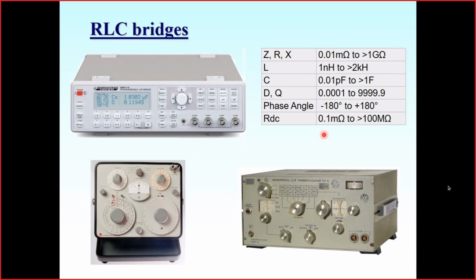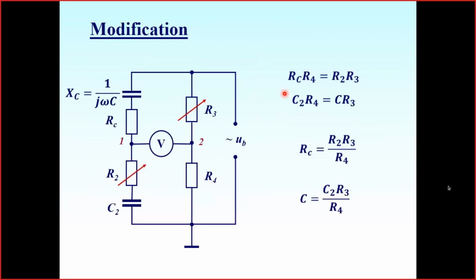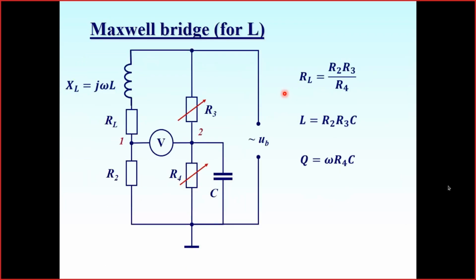We use bridges that measure any parameter we wish, for the estimation of single electronic circuit elements like capacitors, resistance, inductivity. Other parameters may be measured too. For inductivities, it measures not just the inductivity, but also the quality factor. It measures phase angles, and so on. So that was shortly about bridges for AC.